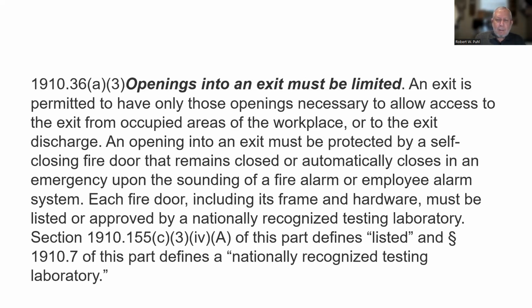Openings into an exit must be limited. An exit is permitted to have only those openings necessary to allow access to the exit from occupied areas of the workplace or to the exit discharge. An opening into an exit must be protected by a self-closing fire door that remains closed or automatically closes in an emergency upon the sounding of a fire alarm or employee alarm system.